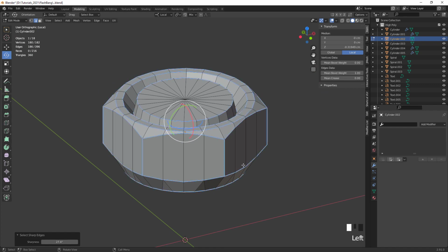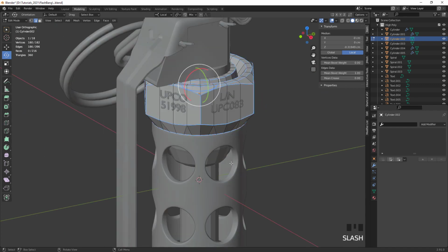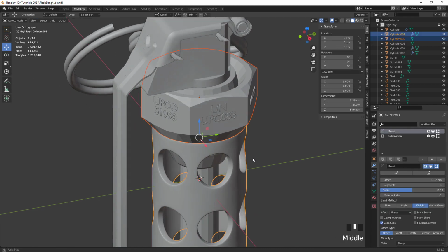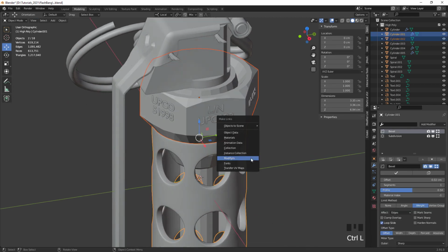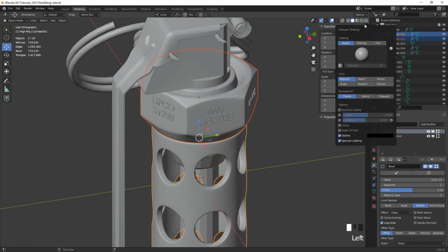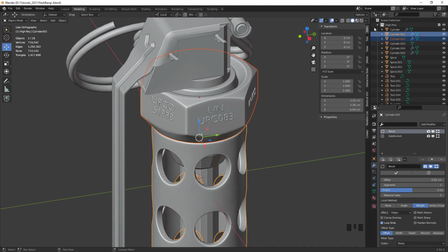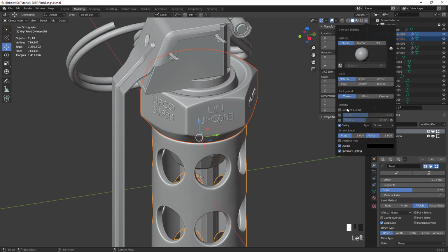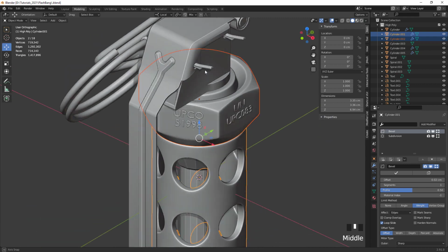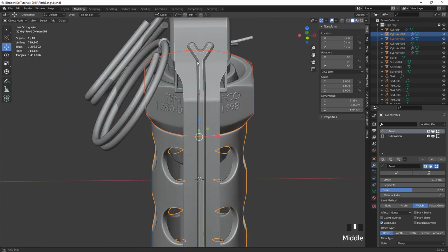And then same thing. And now we can also again copy the modifiers by selecting these two and then Ctrl L and modifiers. So this is a really cool thing that we can do here in Blender, to just copy and paste. We can also enable our cavity here so that we see a bit more the sharpness. We can also turn shadow on, looks a bit nicer maybe.